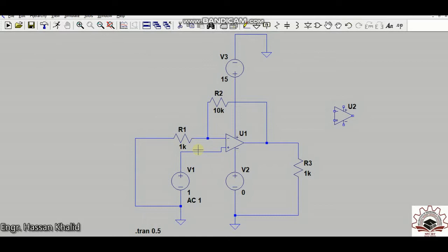Now if I were using the inverting operational amplifier, I must have connected my input voltage with the negative terminal of this universal operational amplifier, and whatever my input voltage was, it will be turned into a negative. For example, if I have given a positive DC, the output will be positive because of this non-inversion. If it is inverting, then the output will be in the negative region. Similarly, if I have given a sinusoidal or AC voltage, the output will be 180 degrees out of phase.